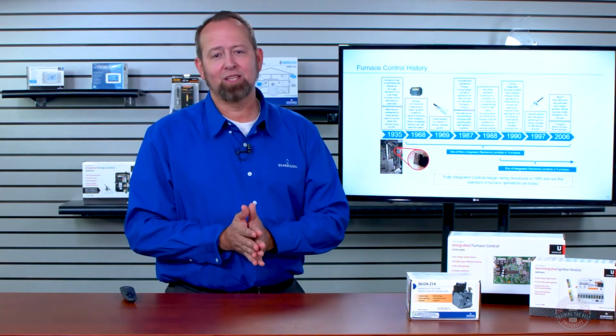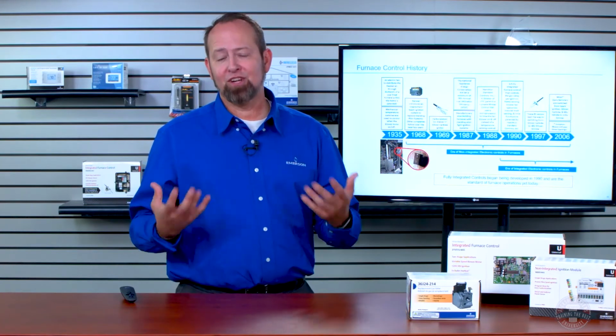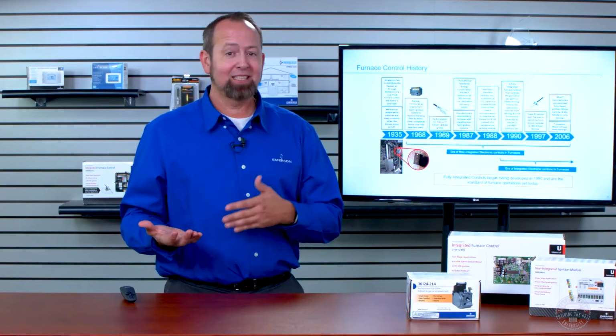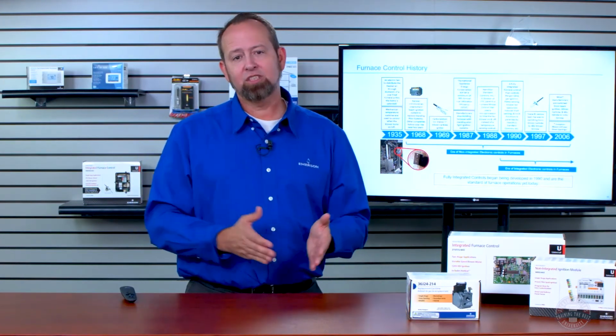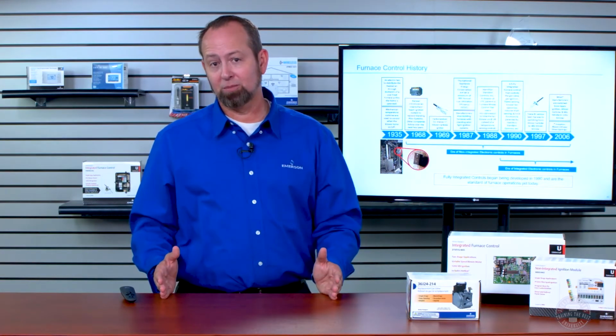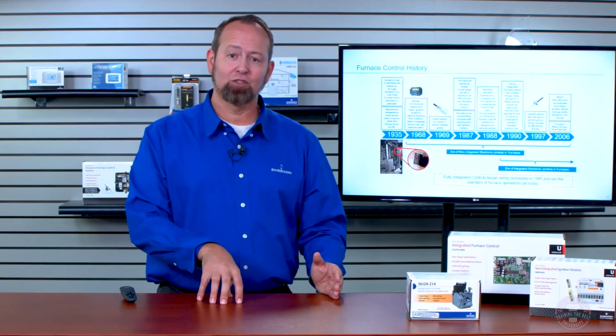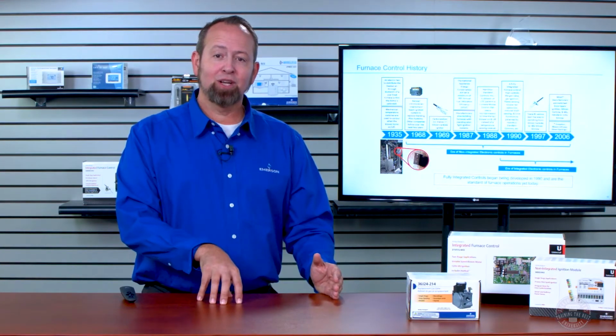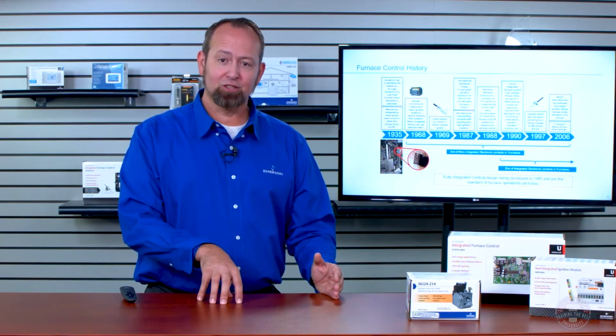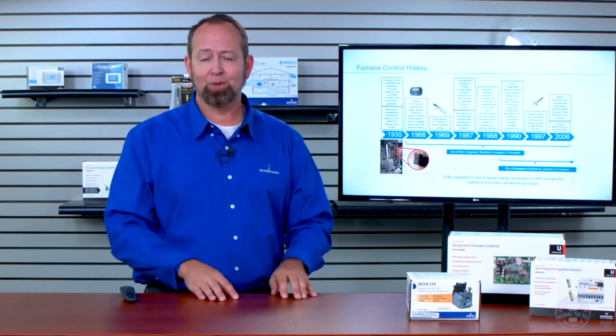And so I share that at this point simply as you're out there looking to replace an igniter: don't just simply check against the model and serial number of the furnace. Check against the control board itself. Make sure that the control board is putting out the voltage for the hot surface igniter that you're replacing.